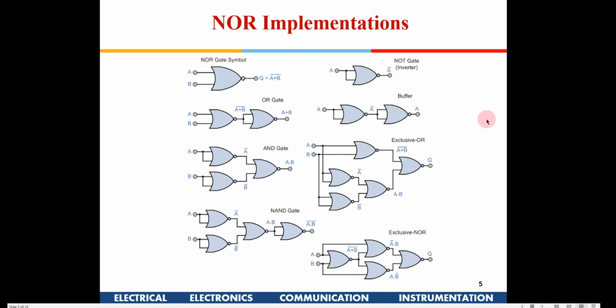You don't want that LED or a bulb directly connected to the microprocessor pin, because it might load the microprocessor. So in between you can use these kinds of gates. This could be a TTL gate, an external IC. You can just put a NOR IC there. Now that LED will be driven by this TTL gate, and it will not load the microprocessor.